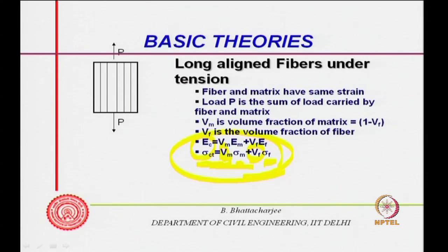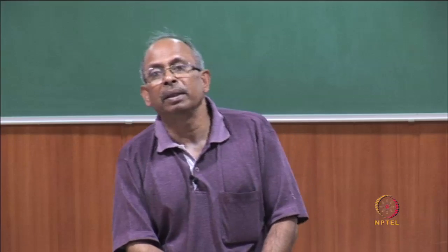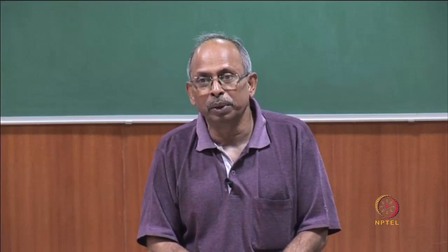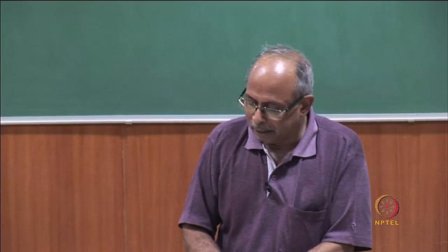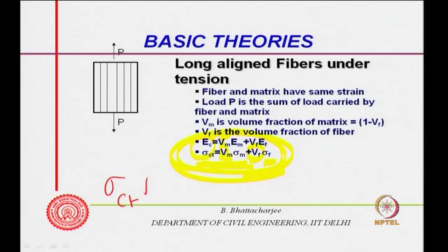introduce it to you. So, the modulus of elasticity of the composite we can find out, which will be a function of the modulus of elasticity of the matrix, that is your concrete, and the volume fraction of the concrete, and volume fraction of the fiber, and modulus of elasticity of the fiber under this kind of loading situation. Similarly, the tensile strength of the composite or tensile stress in the composite at any moment of time will be given by this.